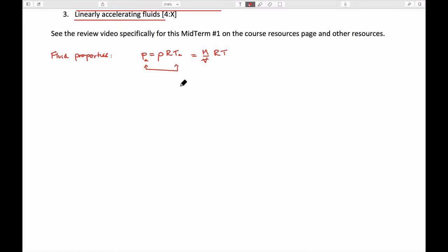And again, the gas law. If you know densities and volume, you can calculate the mass of gas, or if you know that the mass of gas is constant and the volume is changing, you can calculate a density, etc. And you can use that in a variety of different ways. But the most important thing is to use absolute pressures and temperatures.